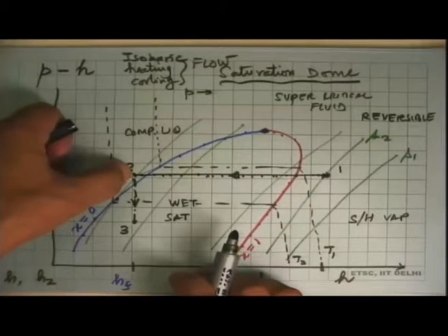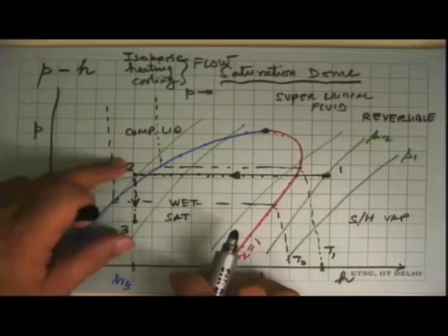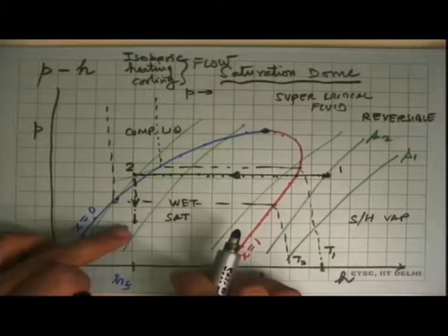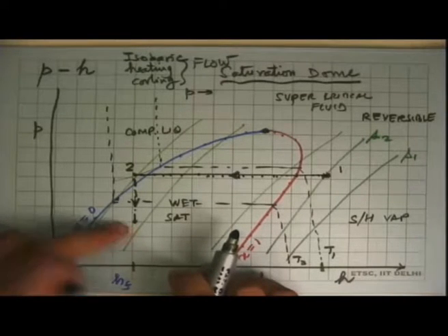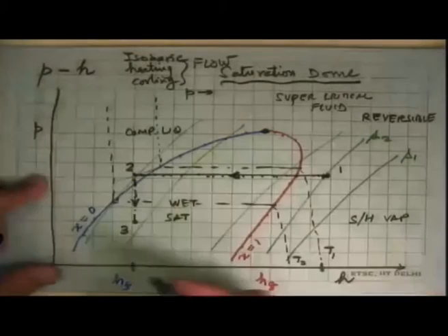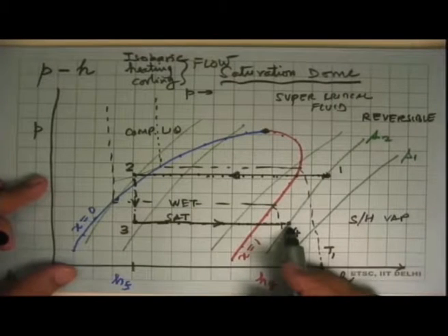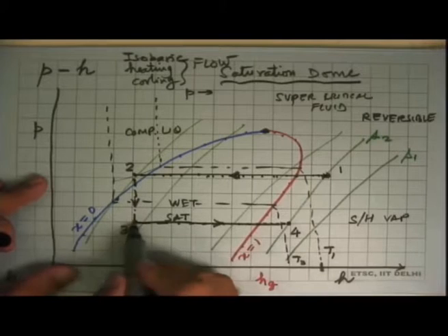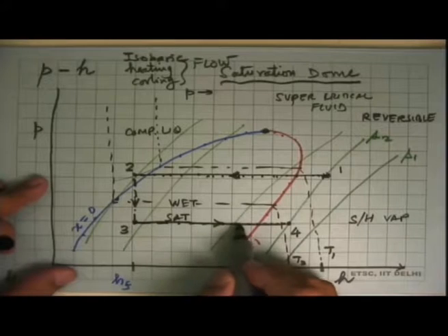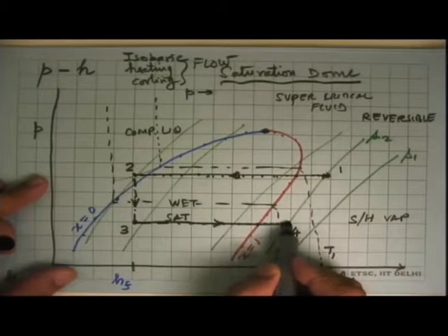So this brings us to another state, state 3, and it tells you that, okay, if we know the specific enthalpy at 2 and the final pressure of throttling, then I know that h3 is equal to h2 because it's the isenthalpic process. P3 is given to me. I have two independent properties, we can do the rest of the calculation. It is at this state that the refrigerant enters the evaporator where the cooling takes place and keeps getting heated up, the wet saturated refrigerant kept getting heated, its dryness fraction kept increasing, became x equal to 1, and then became a superheated vapor.